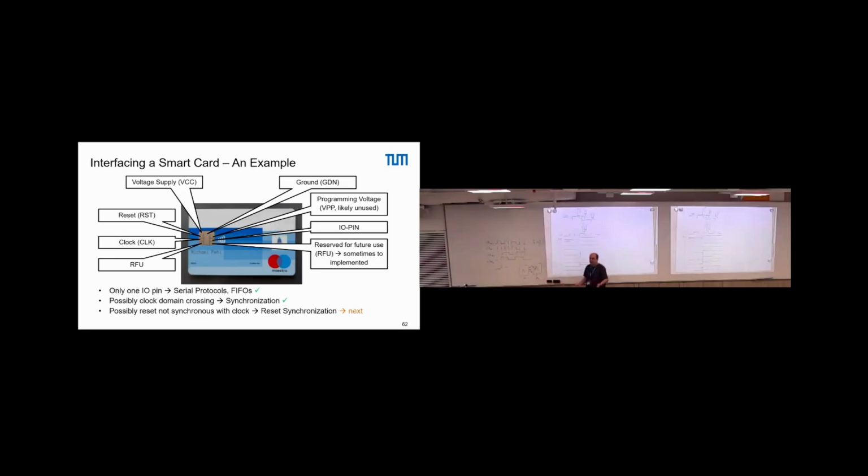So where should something come from? If you switch on your system, you're already in reset state, and automatically you go through the reset. So you do not have to do something on top, where after power up you first force everything to 1, just to remove this 1 later. You do not have to implement additional logic to force the reset to 1 initially. That's why I start here with the reset forced to 0, because that's the usual way to implement it.